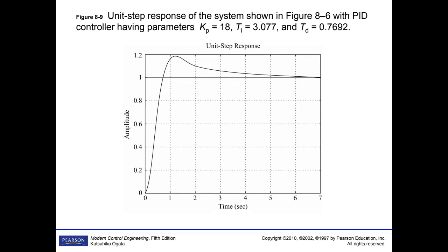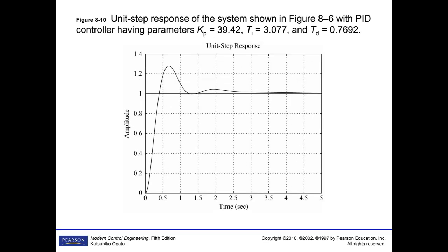And you realize that while you are increasing K, you are not getting any benefit. So there is no point. That zeta is almost constant. So what are you going to do? That means you are going to change the location of the double zero here. Shift the double zero nearer to the origin. So if you assign those double zeros here, the red one is going to change and the green one is going to be obtained.